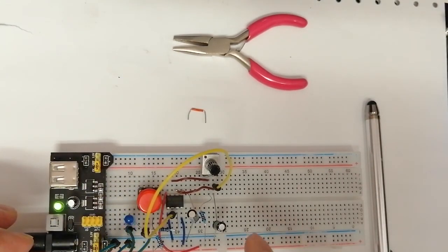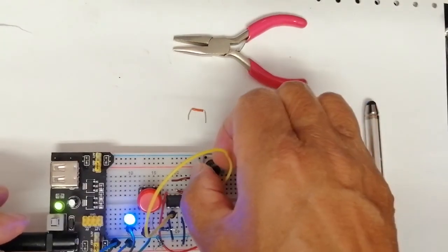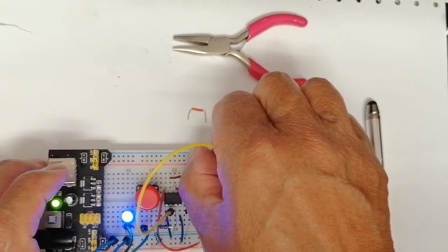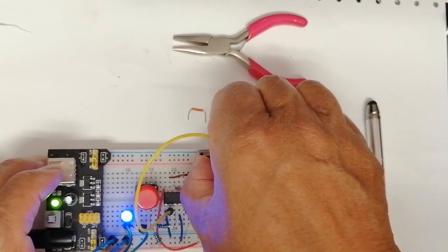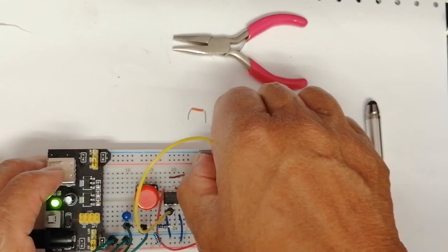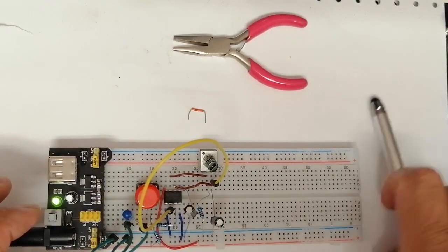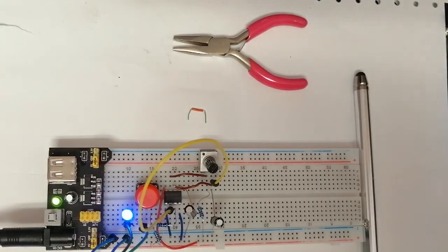The impulse is generated by the output, and the output impulse is going to go through the circuit again. And the frequency is going to change. See, this trailing edge is going to be shorter, so the duty cycle increases. And here you go, this is like a 50-50 duty cycle, 10K and 10K right now, so it's just about right.